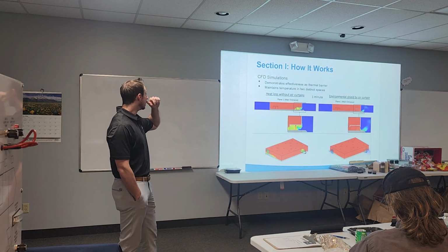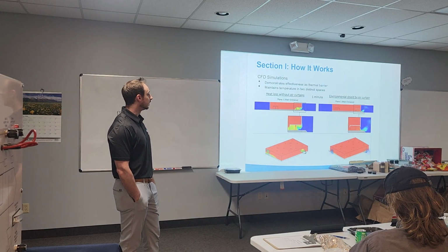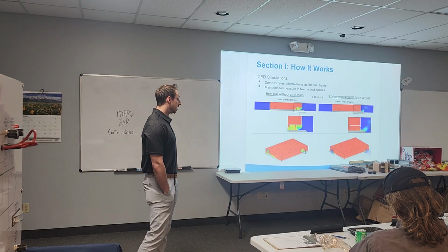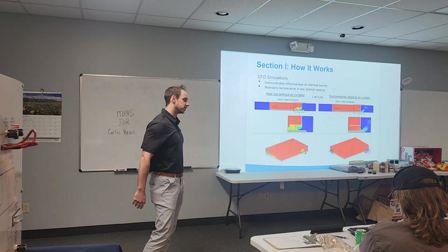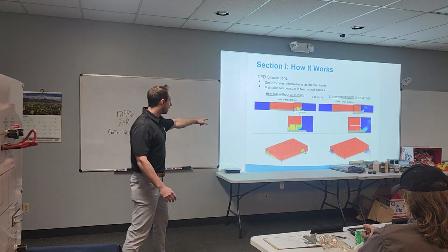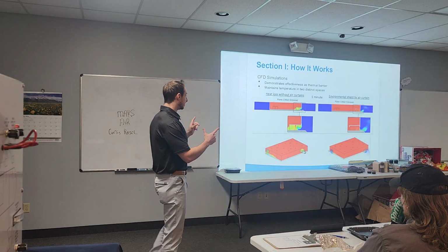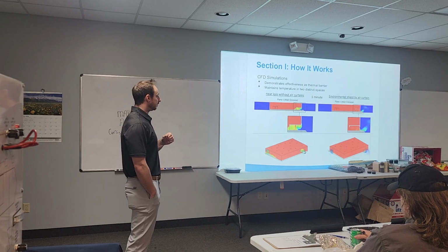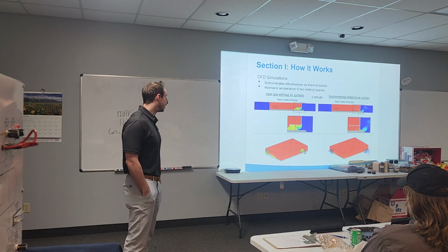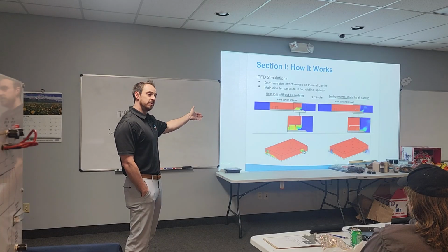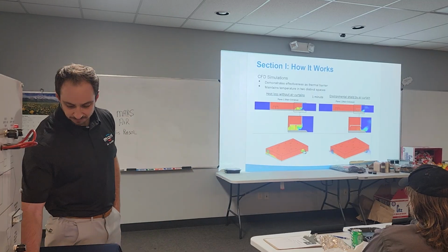Going along that, this is showing the CFD analysis we did. It was actually over a vestibule. A lot of times they can be replacements for vestibules, and a lot of times they work in tandem with vestibules, because designers are comfortable with them. But as you see here, the problem with vestibules is when both of the doors are open, you can still have problems with infiltration. Air curtains stop that, as you can see on the right side with the air curtain on. They stop that from the beginning, but can also be a solution if you end up having a problem with the vestibule. You can use it in tandem with a vestibule as well.